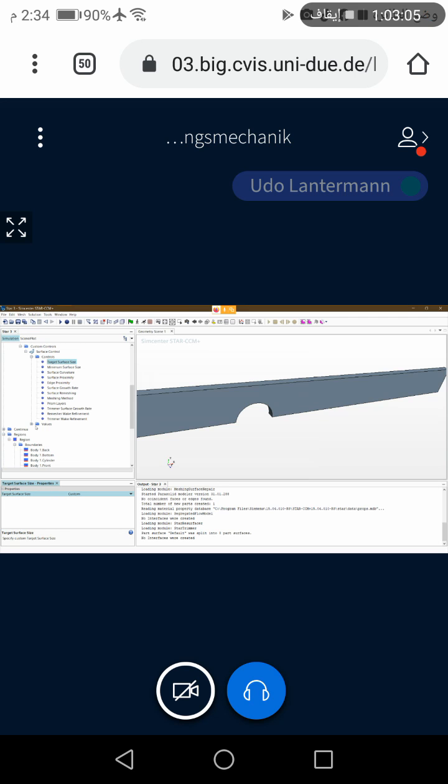And then from values, there will appear the possibility to use a new value. So here we set the target surface size to 12.5%. So again, 12.5 relative to the base size. So again, we choose here this percentage by a factor of 2. So as I told, 100% is base size, next is 50, 25, 12.5, and so on. So we also choose here 12.5.